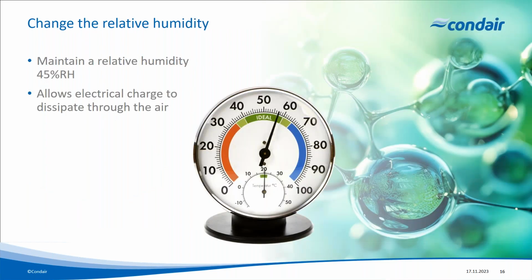So this presentation is about using humidity to combat static electricity. And it's a relationship that isn't very often fully understood. Because when we humidify, what we're doing is increasing the water content in air. And typically, when we talk about electricity and water, the overarching issue is to keep them separate. And the reason that we keep them separate is water is a very good conductor of electricity.